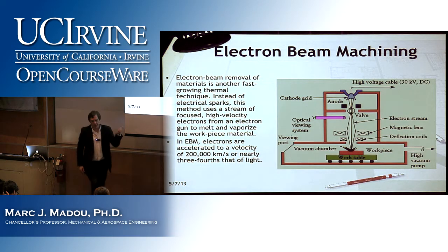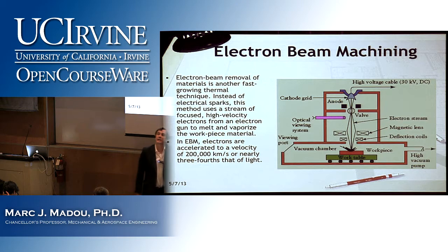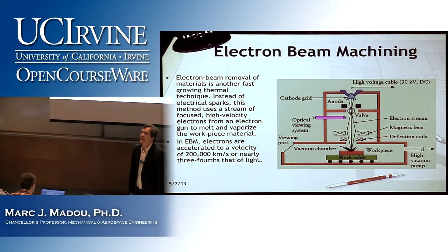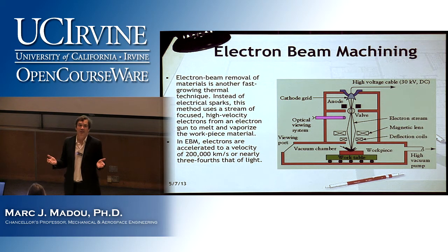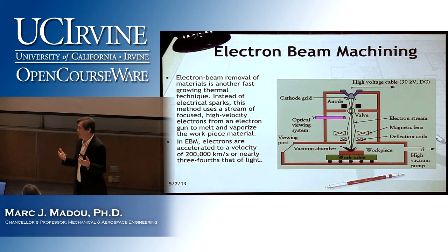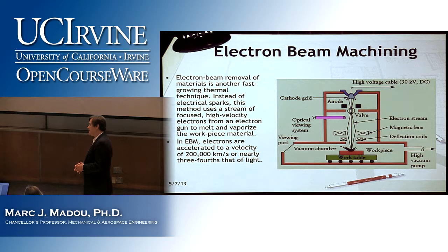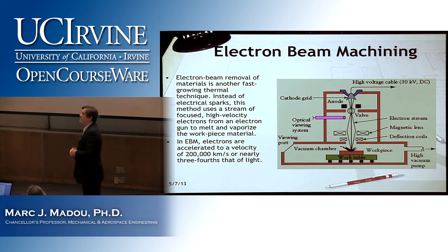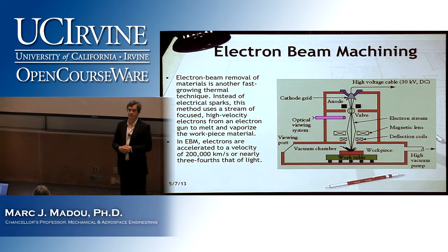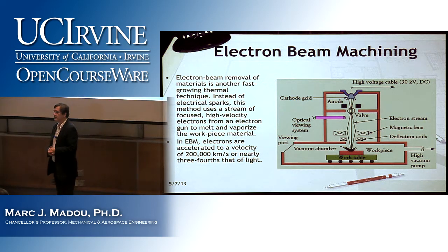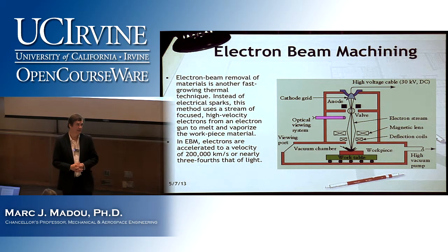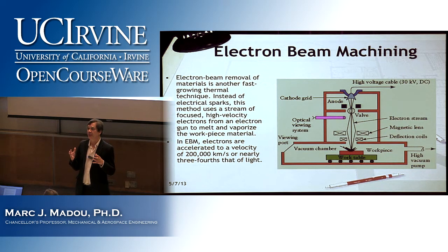Okay, it's just one word about this, and it's actually kind of important. It's gaining importance, and I'll tell you why. So electron beam machining is actually way superior over laser machining because obviously you can cut much, much, much finer structures. The big thing here is that creating an E-beam to do the machining is very expensive. It's also very slow because an E-beam operates in vacuum where a laser beam can operate in air. Right? So today, E-beam machining isn't all that widely used yet.